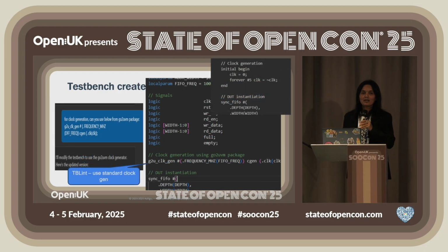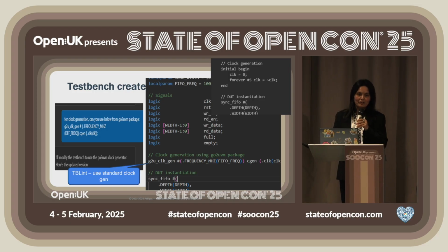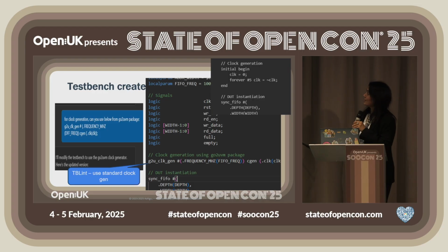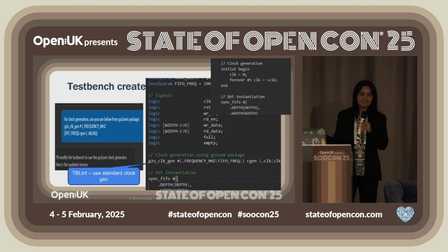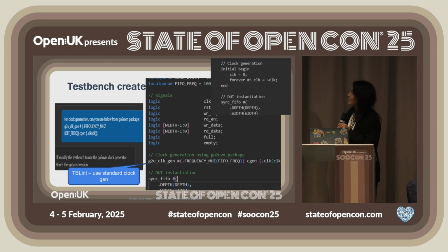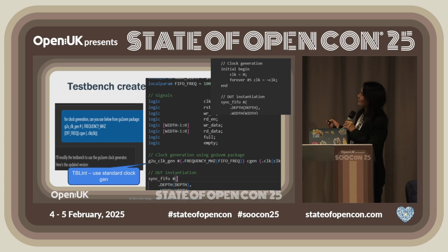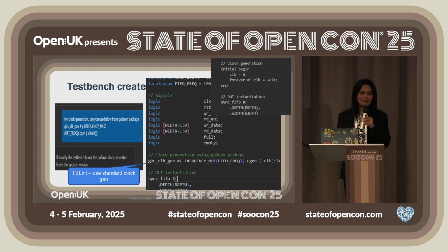All right, so I'm done with the design. Typically, the next task is to develop verification code, a test bench, to verify that the RTL is working properly. Again, it has done a very decent job. If you're familiar with it, there's a test bench with a clock generator and then a test case. That's the flow. But it generated a basic piece of code for the clock generation. It is not really scalable for jitter, or if I want to add additional parameters.